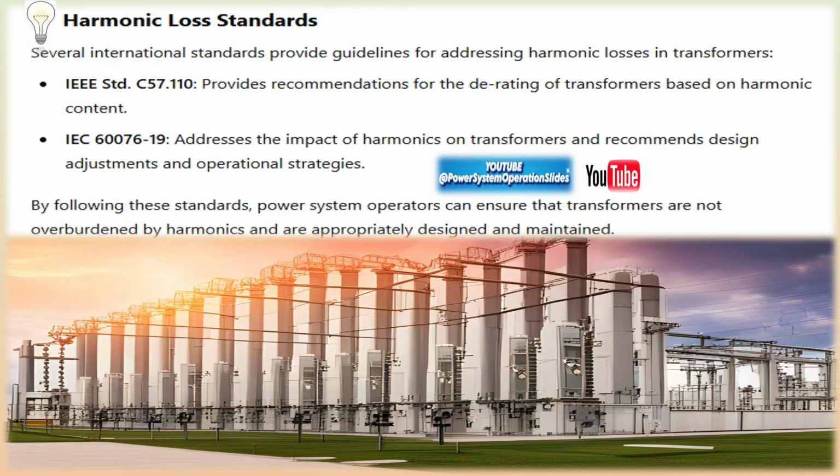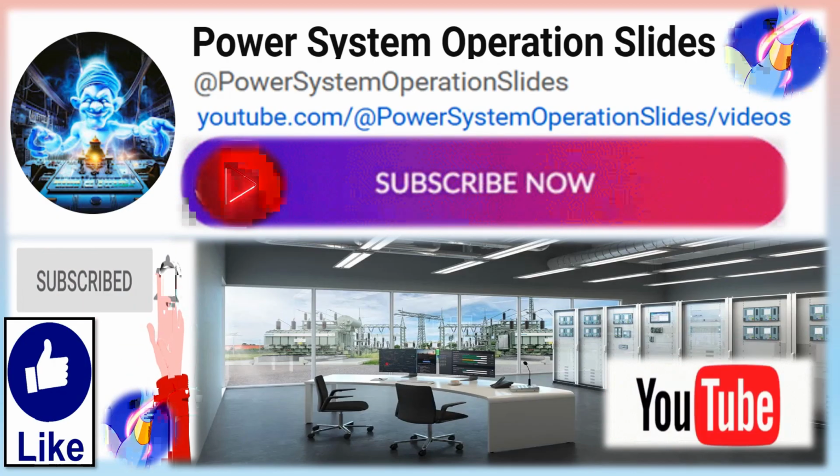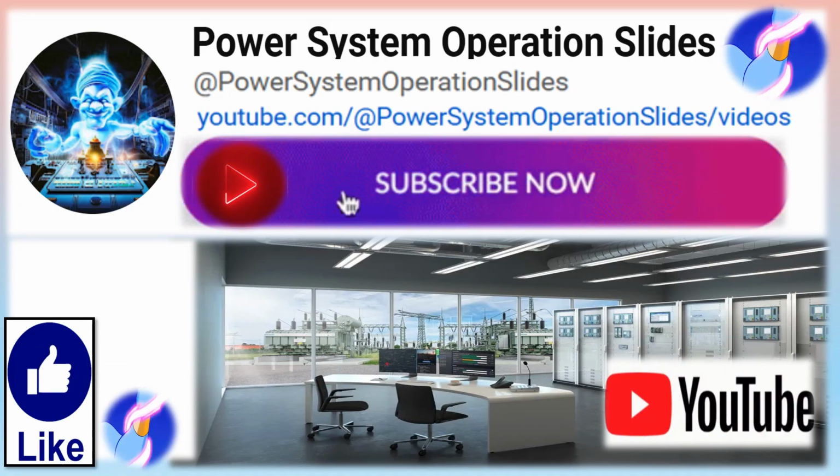Harmonic resonance. In complex power systems, transformers can encounter harmonic resonance, a condition where the inductance and capacitance of the system resonate at a harmonic frequency. When this occurs, the harmonic currents at the resonant frequency can increase exponentially, leading to even greater losses in transformers and other system components.